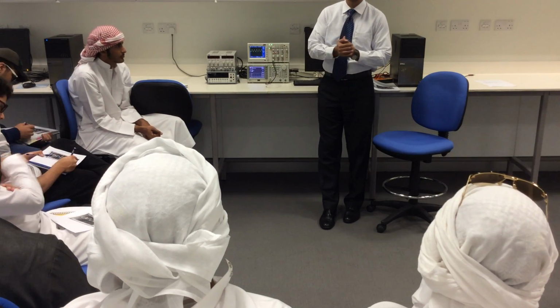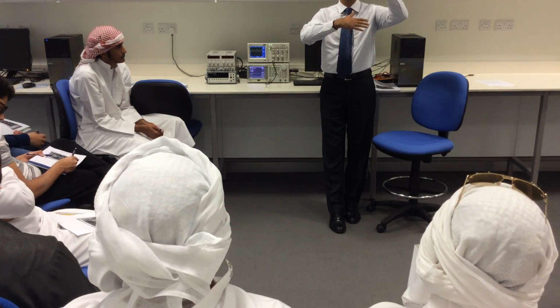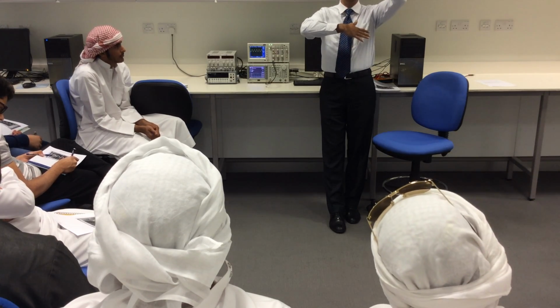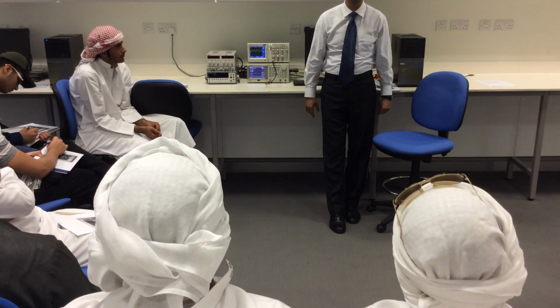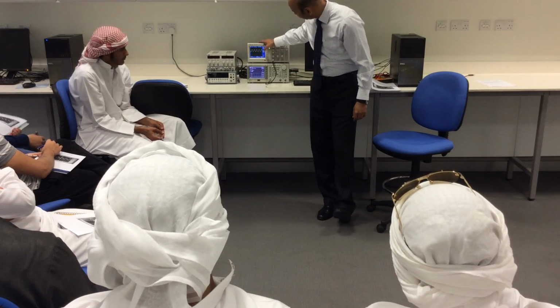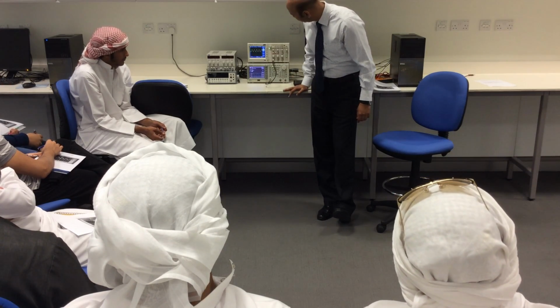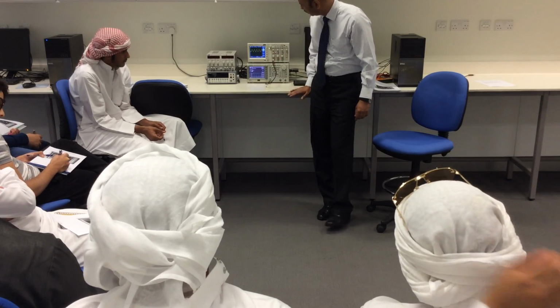Otherwise, it is attenuation. If it is 2x, your signal will be double. 100x, your signal will be 100 times. We just want to see it as it is. We don't want any x multiplication. So keep it as 1x and then auto range again, and you will see the signal here.